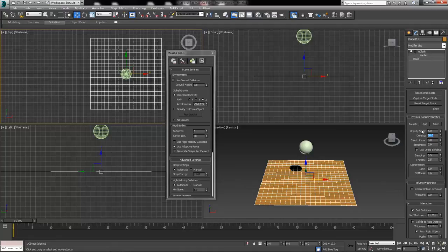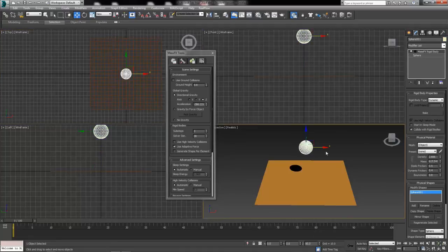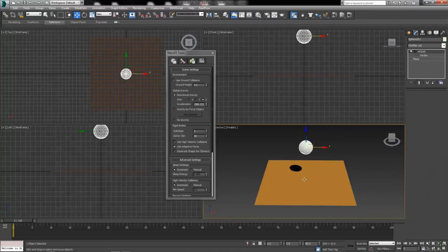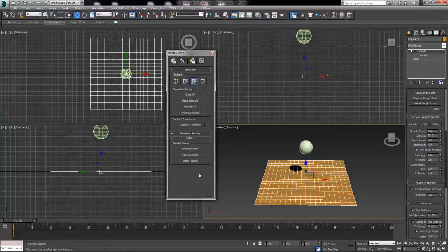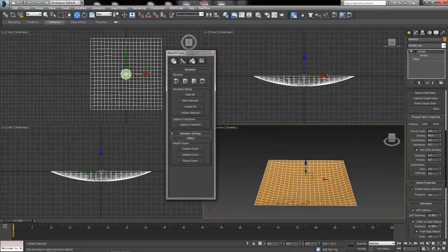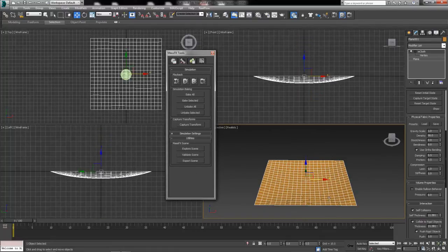We've also got the density, and this is going to be used in combination with our rigid body object. We've got a density here as well. If I set my density, we can round that down to about 2.5. It gives us a mass because they're linked for right now. We could turn that off. But this density, if it is too high for this one, we're going to end up seeing that our sphere, as I think we just did, will fall, catch, and then let go. It's going to treat this surface more like it's a liquid or a semi-solid rather than an actual solid object.